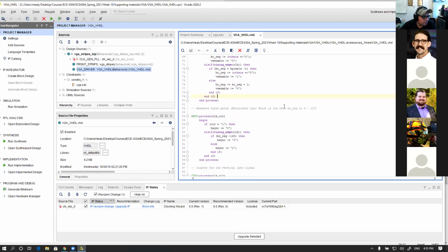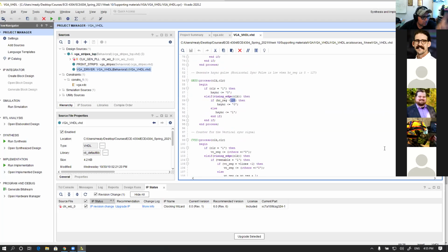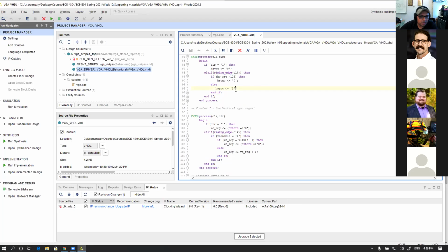Then I'm done with my process of the horizontal, I'm sorry. Now I'm going into the edge synchronization, because the signal is called edge sync, right? That edge sync will be equal to 0. And after certain registers, which is basically the back portion, when I want the sync to go down, I have some numbers I already set up. I make it 128, you can change it to be a generic. And I say don't make sync equal any number because I haven't done it yet. But once 128 happens, which is 0 to 127, basically make the synchronization equal 1.